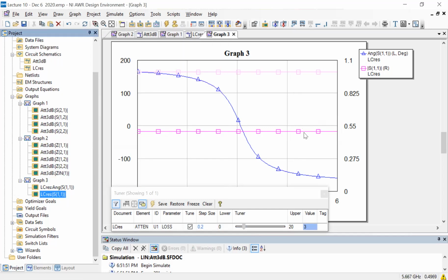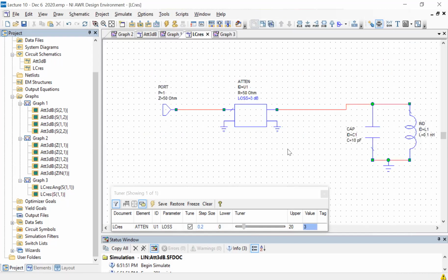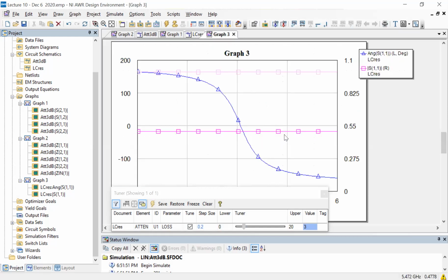So it doesn't mean that it's half power. It's actually 1/4 of the power, because 0.5 squared is 0.25. How can we understand that? It's very simple. The power going this way is going to become half. Half of the power will be lost here. The power will be fully reflected because this is lossless. And then when it travels back again, it's going to experience another 3 dB loss. So it will become 1/2 of 1/2, which is 1/4. So that's why this is at 1/4.